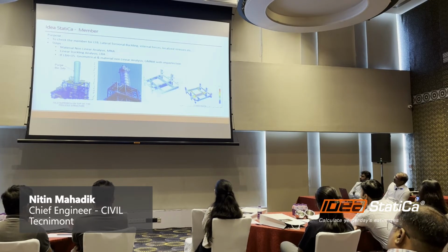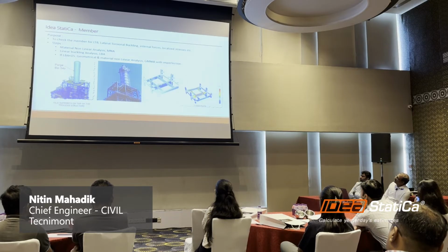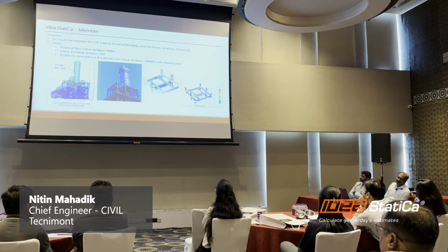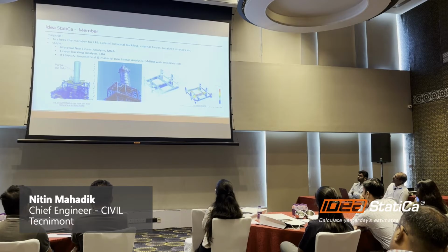So as explained earlier, we followed all those analysis sequences, and as per the code, the LBA is restricted to the value which is shown as 15 in this particular project, I mean Eurocode. At the same time, we check the deflection, LTB, and all those connections and members to ensure that there should not be any adverse effect under the action of earthquake and wind, which is very difficult to analyze in a global software, even in SAP. So this benefit of IDEA StatiCa enables us to put the steel at the right place rather than adding redundancy in the structure or reducing the unused member. So that is the benefit we are drawing from IDEA StatiCa.